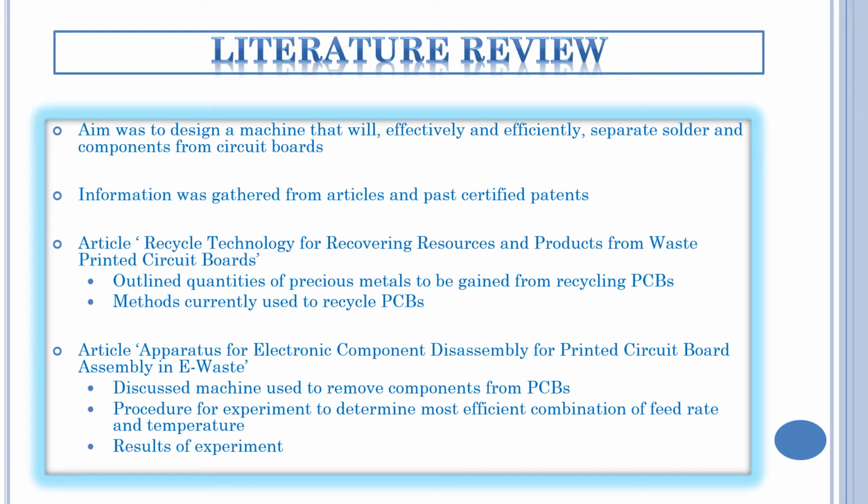The machine highlighted in this article uses a series of rollers and steel brushes to crush the components and sweep them off the circuit board into a collection system. As the motherboards are fed into the machine, they are heated by infrared rays at a temperature that liquefies the solder. The data collected from this test revealed that at a feed rate of 1 centimeter per second and 250 degrees Celsius, there was 94% component removal.